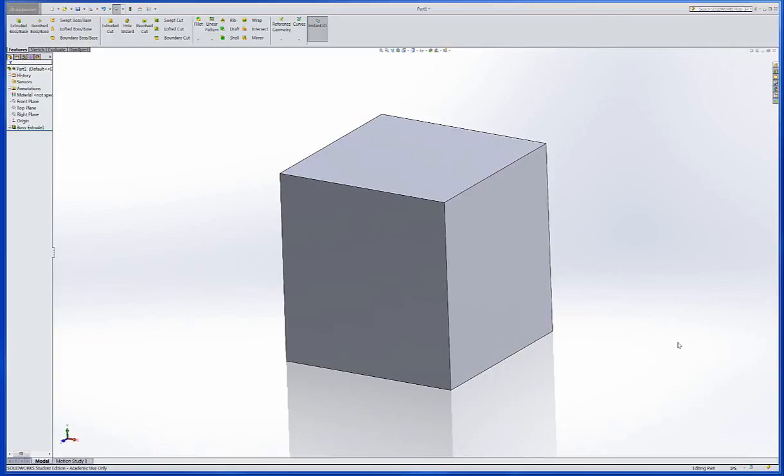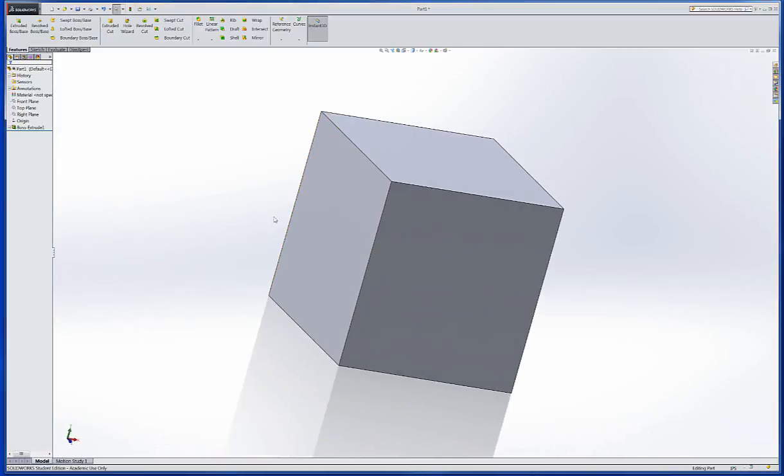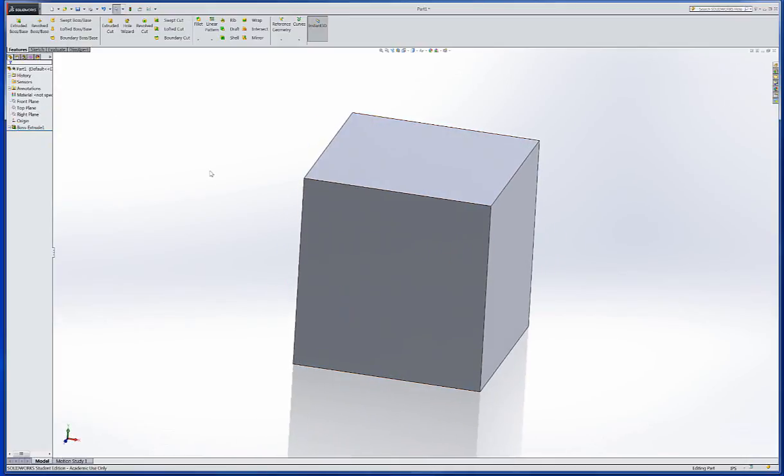For this video, I want to show you how to punch a hole through a particular part. We'll go through several different features of the hole command, but the basic thing we want to start with is how to put a hole in a solid part. We've already got our solid constructed. We did that in another video, and we can see that it is a solid. It's got the boss nomenclature here, so we're good to go there.